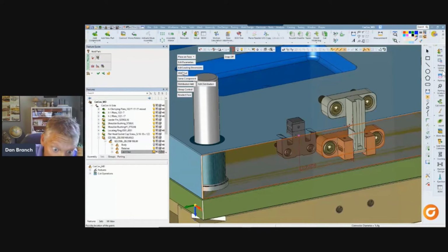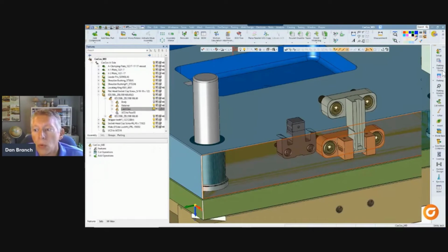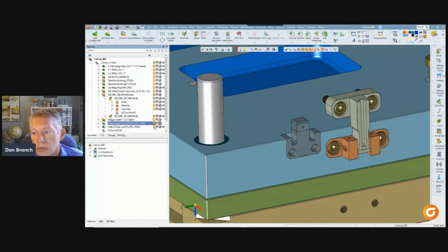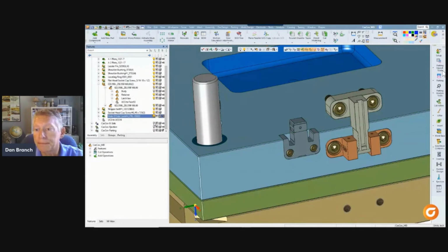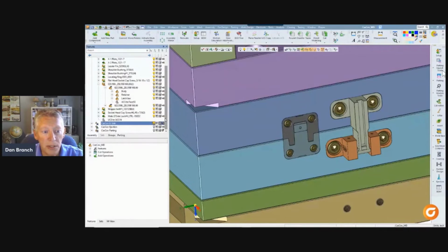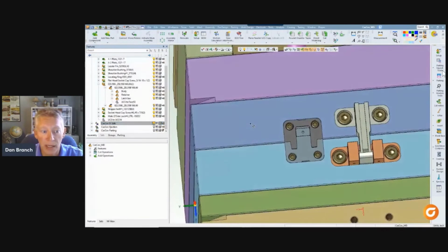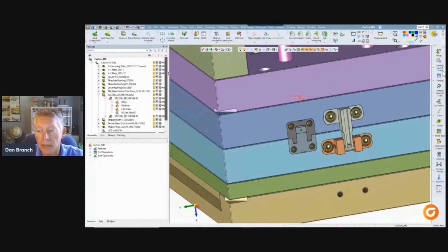Another option here is "with cut," and that is definitely a good one to use. Cut means that I want the part being added to make its own holes and pockets in the plates, which I do. Now, by hiding those newly added parts, I can verify that the pocketing looks good. This ability to cut in the pockets comes right from the smart catalogs. The type of pocket and clearances are all relative to the parts, so no matter what edits may take place later, I can be sure that the plate machining work is going to be correct. Now, as expected, the B side of the tool received the rest of the side lock components and, of course, the corresponding mounting holes.